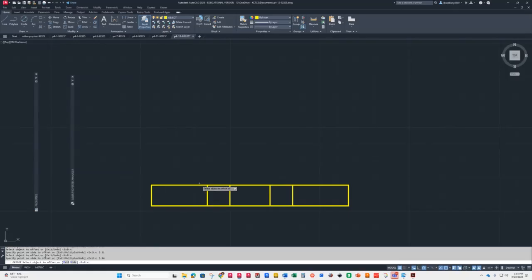Now, some people get confused. They think that the 4.5 is from the bottom of the part, and I did say 4.5 tall. Well, it's actually 4.5 plus 0.62 if you're actually looking for the real total length. So I have some people draw it where they have the length of that vertical piece at 4.5, and some people draw the whole thing 4.5.